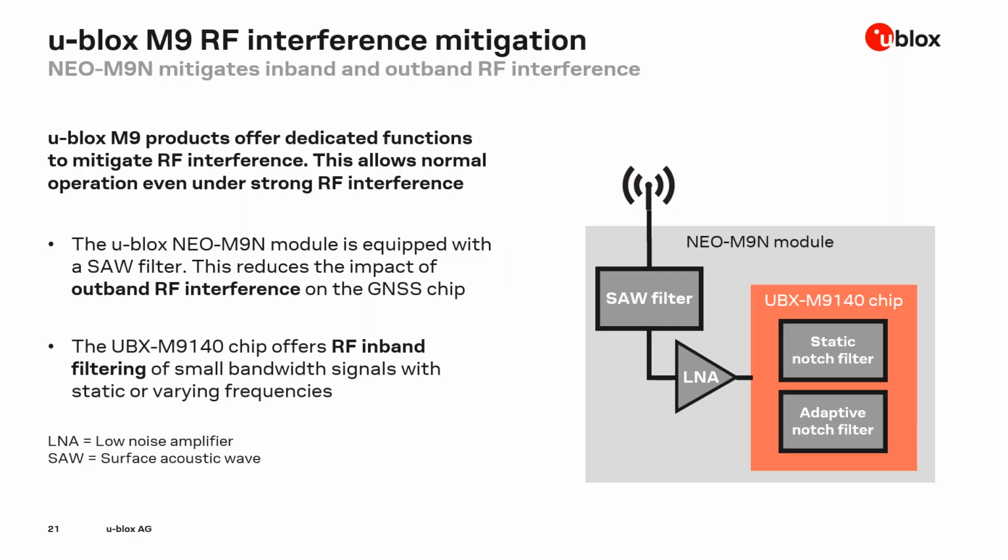So looking at it now, I refer to the u-blox M9 product, and especially I look at a module product. For the module product, you see a very rough figure on the right-hand side of how it's built. Inside there's the u-blox M9 chip, and there is an LNA and some RF filter, a surface acoustic wave filter, connected to the antenna.